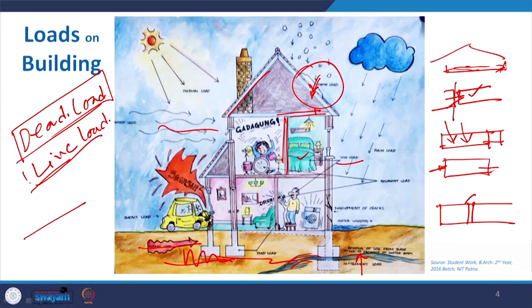Now, before we go further, in structure we normally say that one is your foundation and underground structure, and then what is above that is basically the superstructure. Many a time I will use this term superstructure. Apart from that, here it is shown, if you see it clearly, something dotted, some deformation. This is the initial foundation level, and here it went down because of unequal settlement of the land, and sometimes it may happen due to the compactness of the soil, compactness of that particular area.